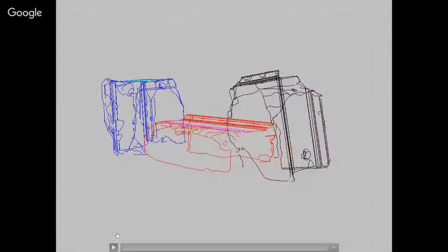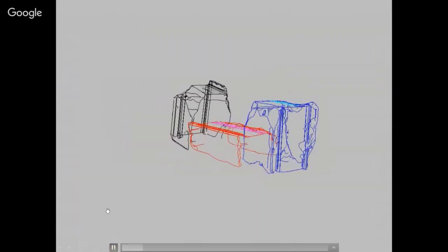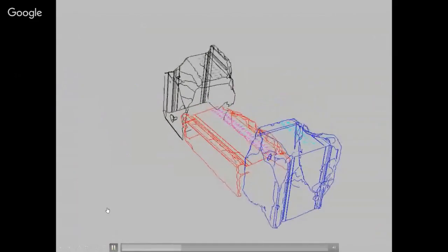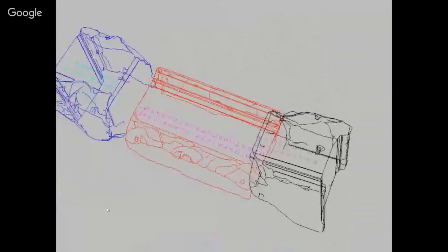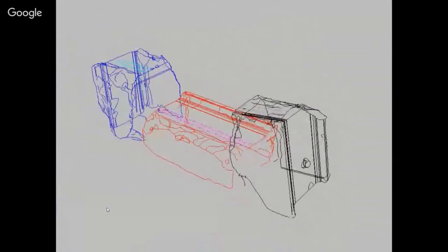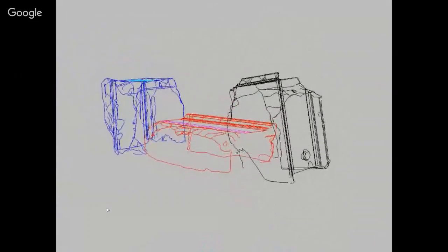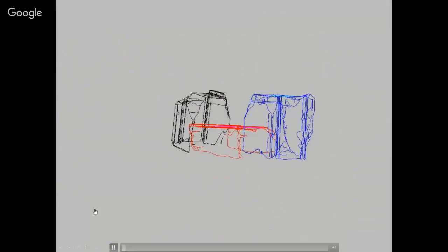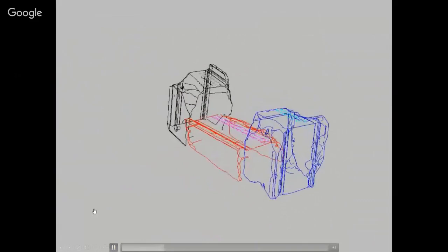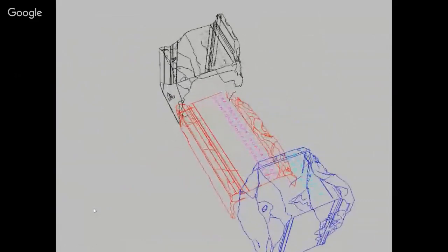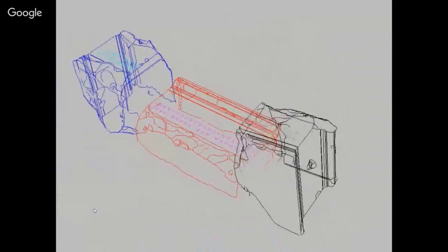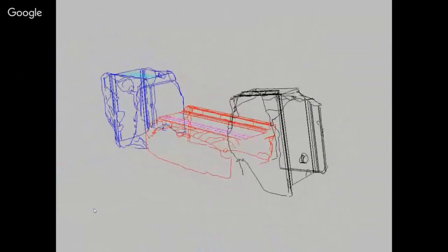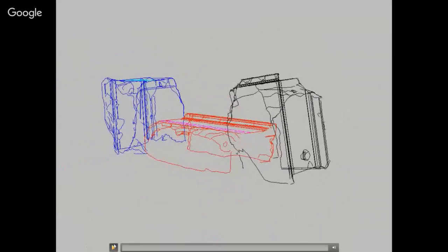This is the raw data that comes directly out of the total station. I was just moving the total station around the blocks, and this is the documented data. I have done no manipulation at all, just downloading the data from the total station and taking it to CAD. Okay, when I was recording it, I did have different layers for the texts and different blocks so that they could be separated, and you can make them join together.